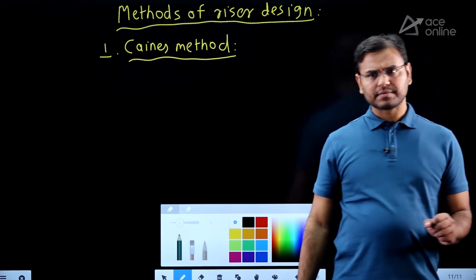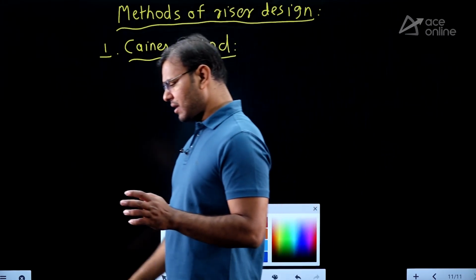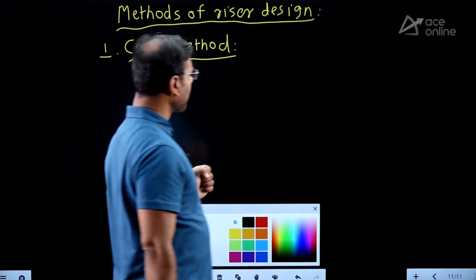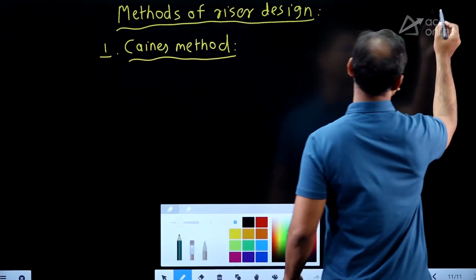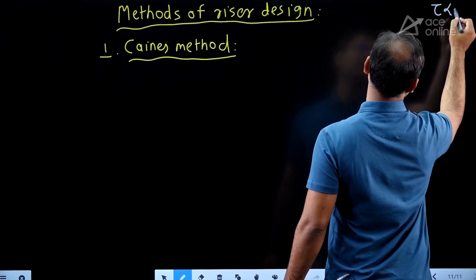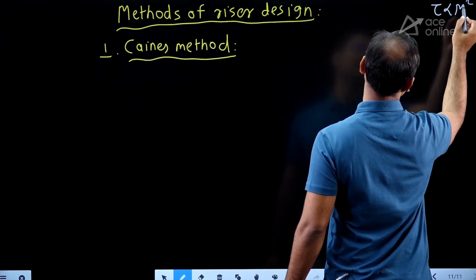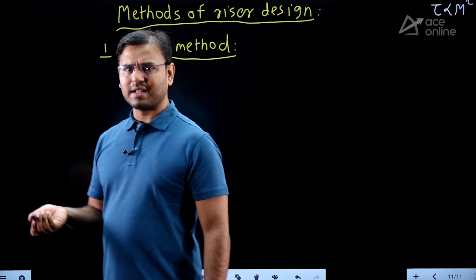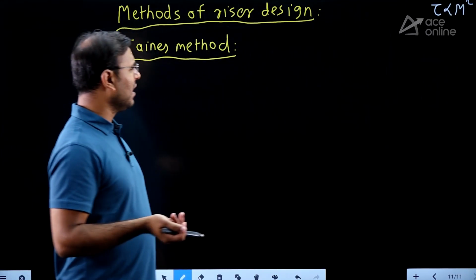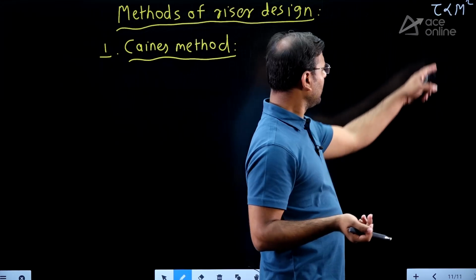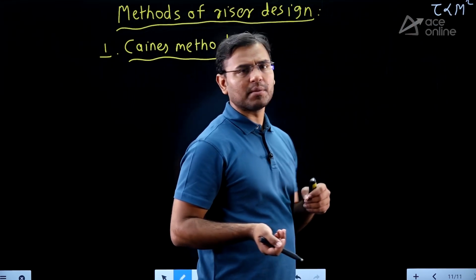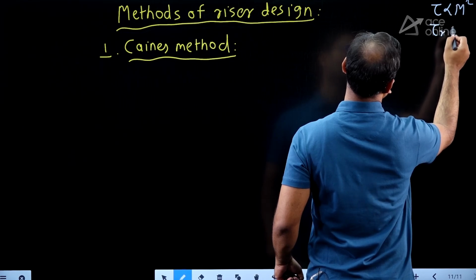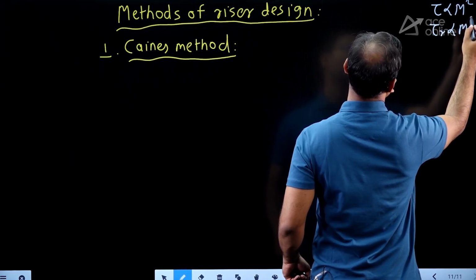Okay, guys, here now two types of modulus are going to come in the picture. First, for solidification, we wrote that tau is directly proportional to M square. Then, guys, this capital M was the modulus for casting cavity, and this tau is the solidification time of casting. Now I am writing here tau r is directly proportional to Mr square.